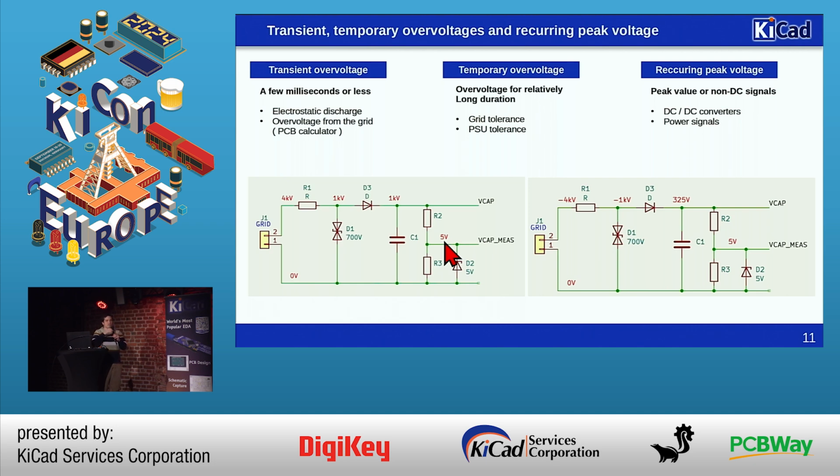Basically, you should group your net classes depending on the voltage. Some other proprietary software tools don't use the word net class for isolation, but it's the same idea. It can be physical groups or something, but I just want to group all of them, and between all of them there's no more than 10 volts difference.